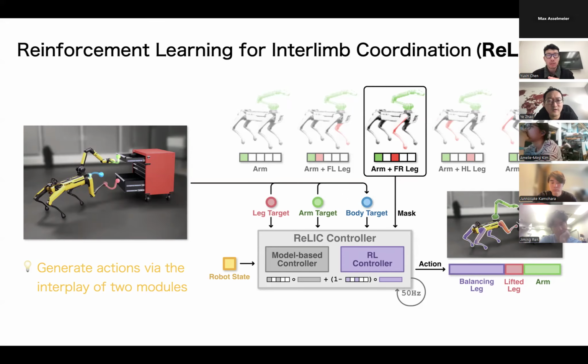We have some other observations about this. I think they couple the upper body and lower body controllers. When we do locomotion, the local motion usually causes a lot of vibrations to the upper body. If you want to stabilize the upper body for stable manipulation tasks, it's very challenging.